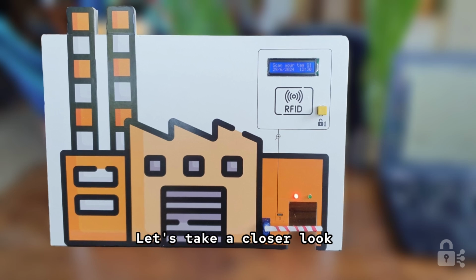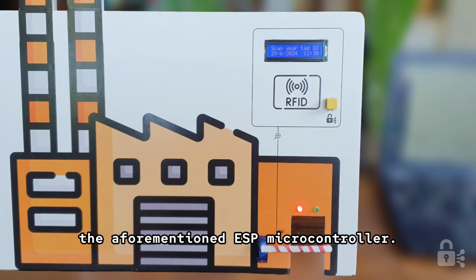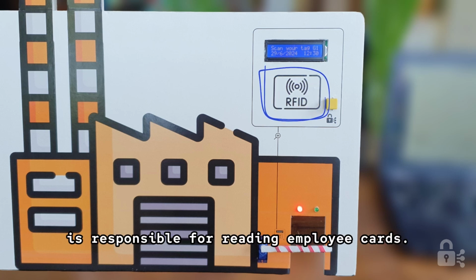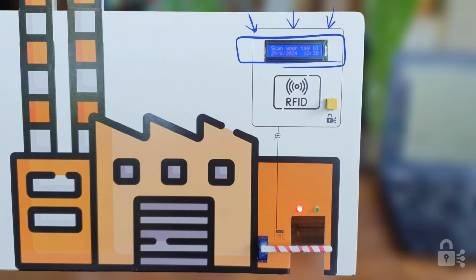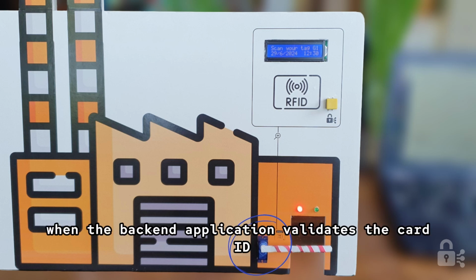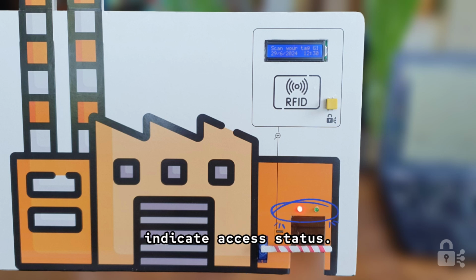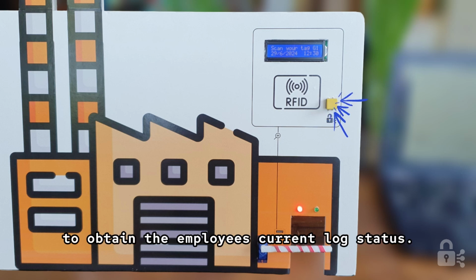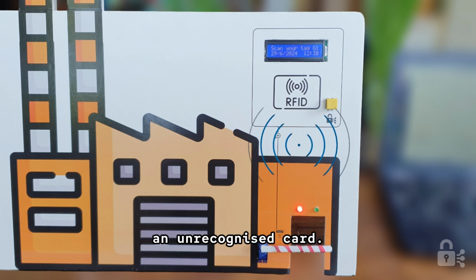Let's take a closer look at our entrance gate model now. All components are controlled by the aforementioned ESP microcontroller. The RFID reader is responsible for reading employee cards. Just place the card on it. The LCD display shows current information. The gate barrier is controlled by a servo mechanism that raises it when the backend application validates the card ID and grants entry permission. The red and green LEDs indicate access status. Press the information button while placing the card to the reader to obtain the employee's current log status. The buzzer is an alarm that is triggered in case of an unrecognized card.